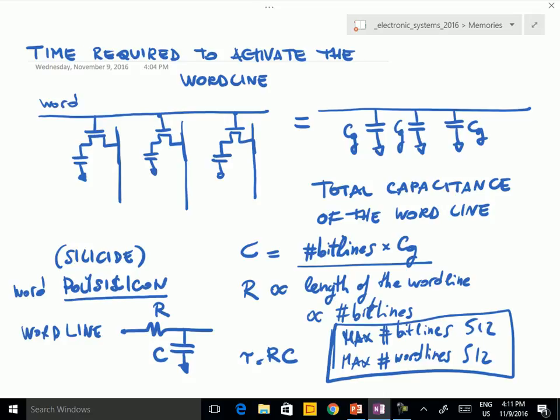Okay? If we want to have a larger memory, which of course we need, we have to put many banks. Let's say we have to make an array of memory banks. So to duplicate all the word decoder, the bit line decoder, the sense amplifiers, every 500 word lines and every 500 bit lines. This is still what is happening in practical circuits now. Okay.